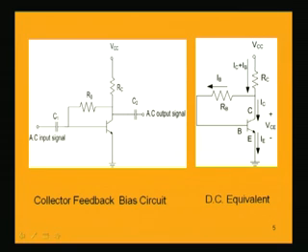So, we need to find out for this biasing scheme what is the collector current, what is the collector to emitter voltage, in order to know the operating point Q, which is known as quiescent point or silent point, means without any signal when we first find out the DC condition. When you apply the signal for amplification, then of course, we will have to analyze it in a different way, drawing the AC equivalent circuit, and that we will be taking up later. So, for the time being, now let us find out what will be the IC current, what will be VCE.